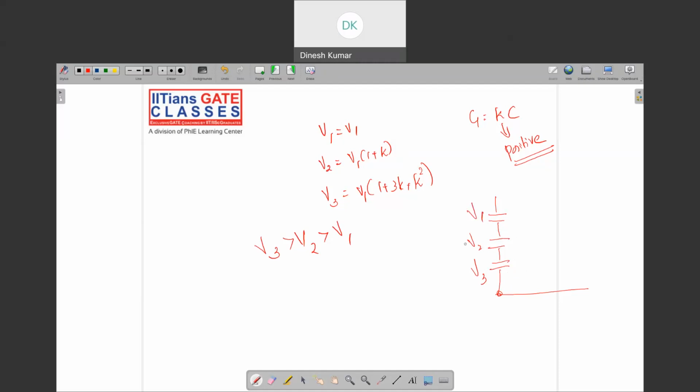If you look, this is not exactly linear, right? It is going like something parabolic or higher order. So we'll get something like the most voltage concentrated here. More and more voltage will be concentrated near the conductor.